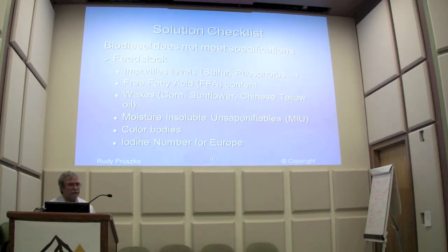Is that just a cold problem when you've got the waxes in the fuel, or are there other issues? It's a cold problem. You could run the corn oil through the biodiesel process. The waxes tend not to steal too much catalyst. They tend not to make a lot of esters. They end up just being waxes in the final product. But it'll fail the cold flow properties, and those waxes will end up on filters.